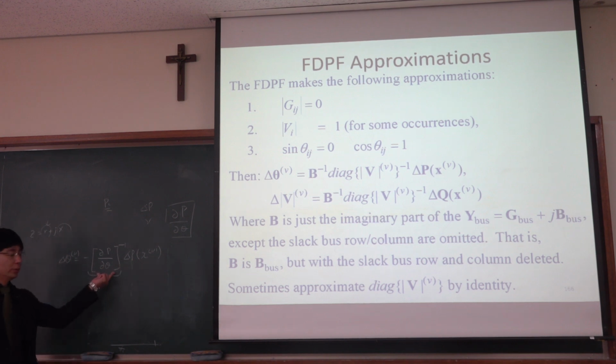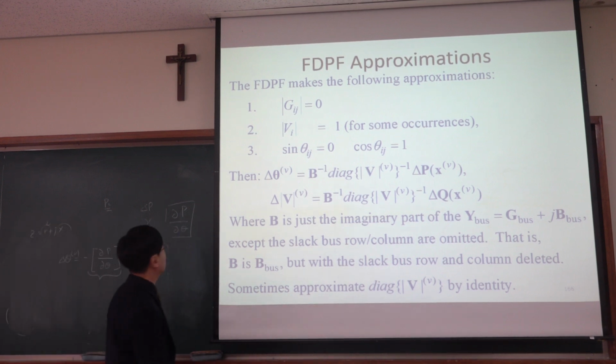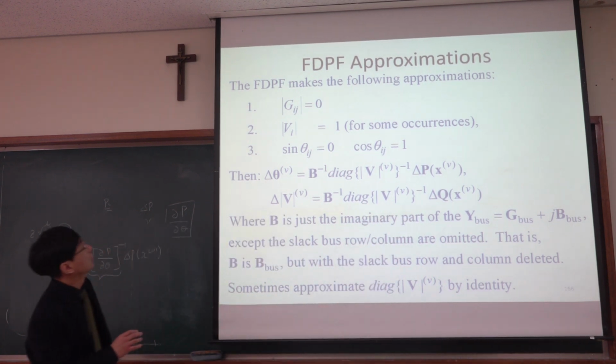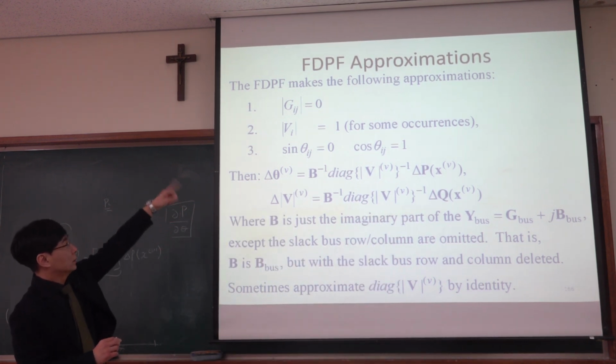We do not need to compute the Jacobian of active power with respect to phase angle, but that is replaced by this one. And that is because of that assumption.